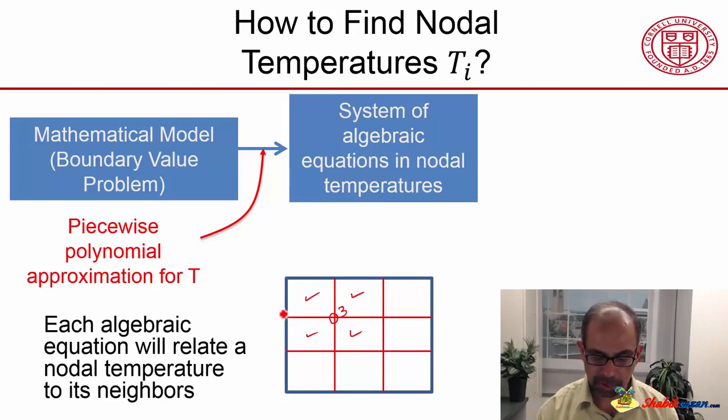And then you pick out all the nodes that are attached to each of those elements. So this element is attached to these 4 nodes. This element is attached to these 4 nodes. And then you have these nodes coming in and these nodes. Which means that the algebraic equation at this node will relate T3 to these other values. This node is not connected to this element, so for instance, those nodes won't be involved in writing that relationship.